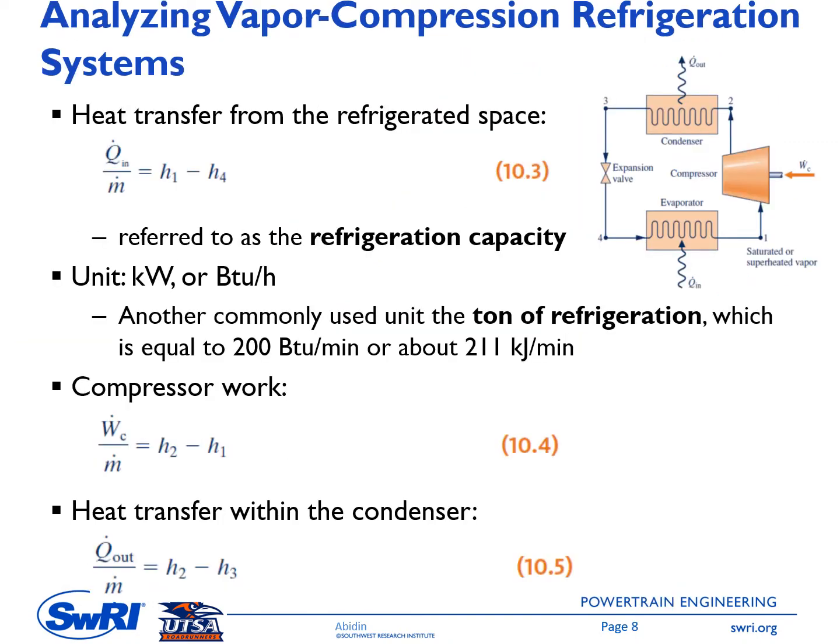So we have this refrigeration system now consisting of evaporator, then compressor and condenser, and the last component is the expansion valve. And also the phase at state 1 entering the compressor is either saturated or superheated vapor. So it means we have 100% vapor. Because of this condition, it is usually also called a vapor compression refrigeration system.